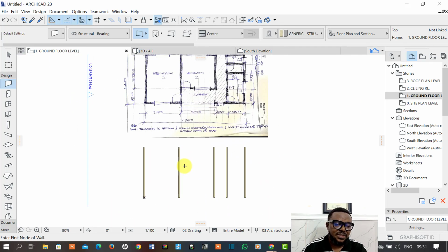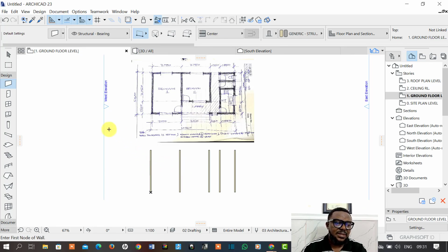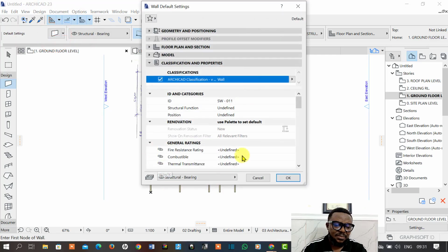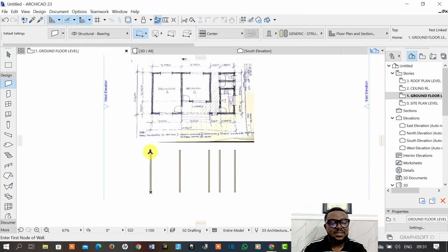So now let's do the horizontal walls. We are done with vertical. So you can select your wall again if the wall is not selected, and you come to this point at the top and you see the tick. You click on that point. It means that you have snapped that point. And you click to the end. We've put that wall. So we select on that wall and offset downward.